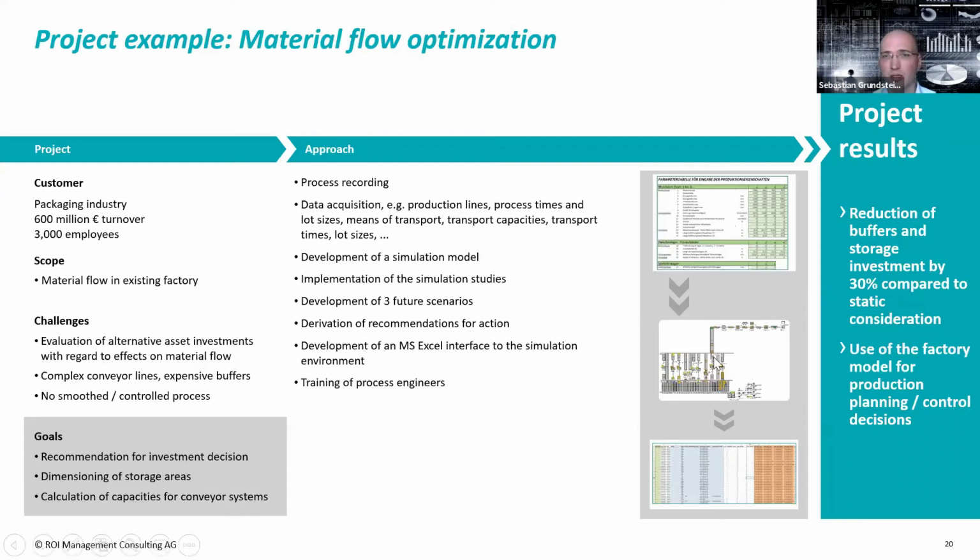And what we did, we collected the data from the past, all the data: process times, lot size, downtimes, and so on. We took the past orders of a year and modeled the behavior under certain scenarios to dimension the buffers and the storages, and to give a recommendation for the investment.